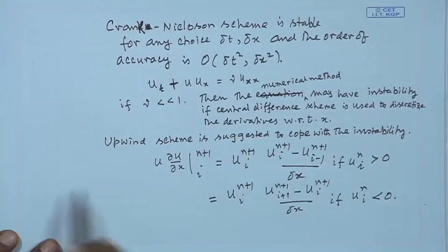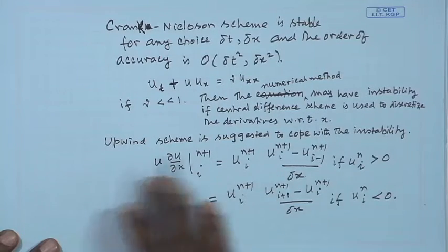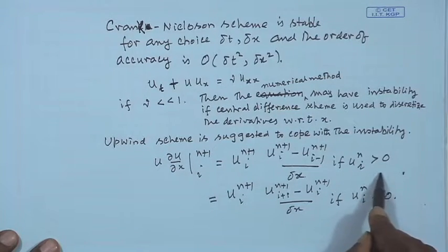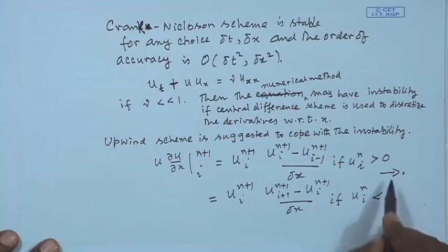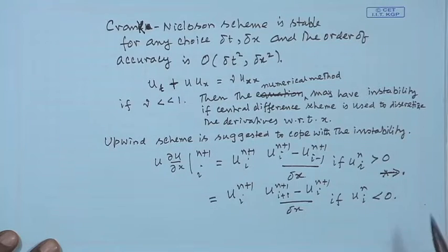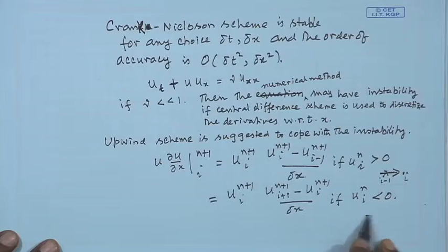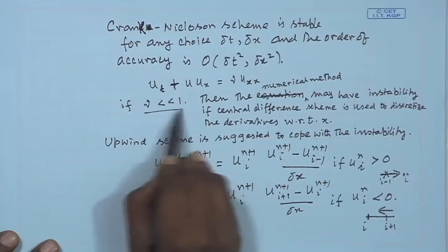So, this is the upwind, that is along the direction of the wind. When the flow is coming forward from the backward direction, at this point i the flow is like this way. So, this is your u n i, and you use the points which are backward of yours. You are at i, so you take i minus 1. But when the flow is coming the other way, you use the information from i plus 1. So, that imparts stability even if nu is very low.